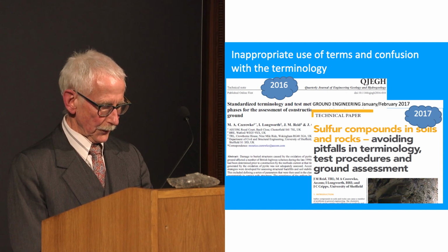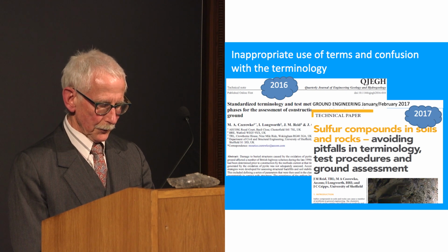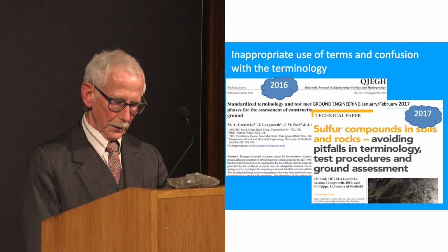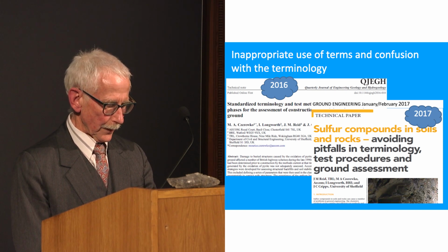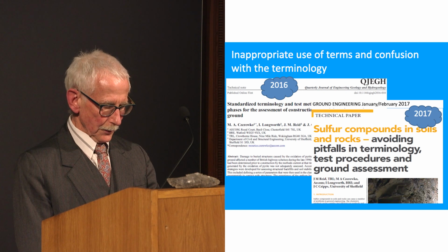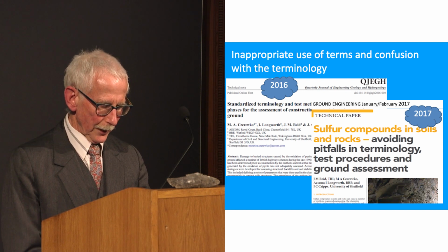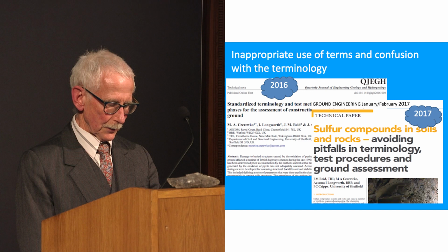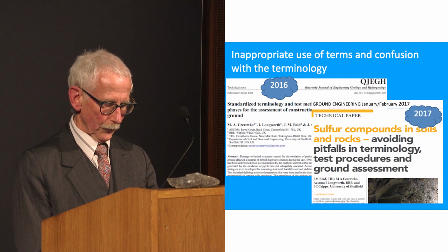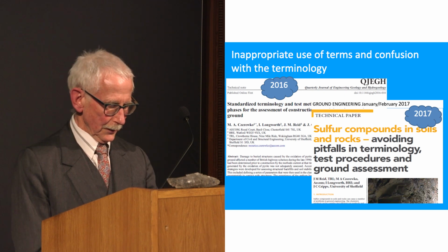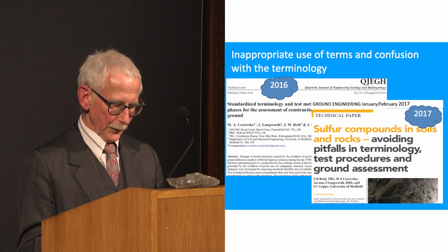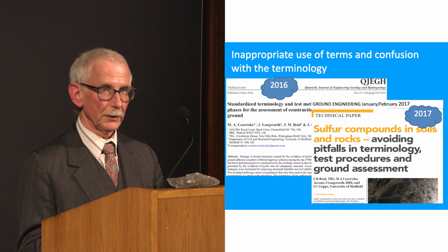We drew attention to the potential inaccuracies in assessment of pyrite using standard EN 1744 Part 1, 2012, because this became the standard for chemical tests for aggregates under the Construction Products Directive of 2004, and with harmonisation of standards in 2016, it became the default standard for chemical analysis of aggregate materials in the UK.